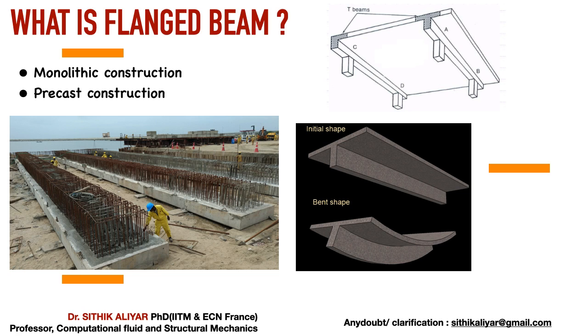Okay, so why do we have to consider this way? Because so far we have discussed many examples in single and double reinforced sections. In the single reinforced section, for a given width, depth and reinforcement, we saw the maximum moment the beam can take is approximately 100 or 150 kilonewton meter. In double reinforcement it extended up to 200, 220, 250.